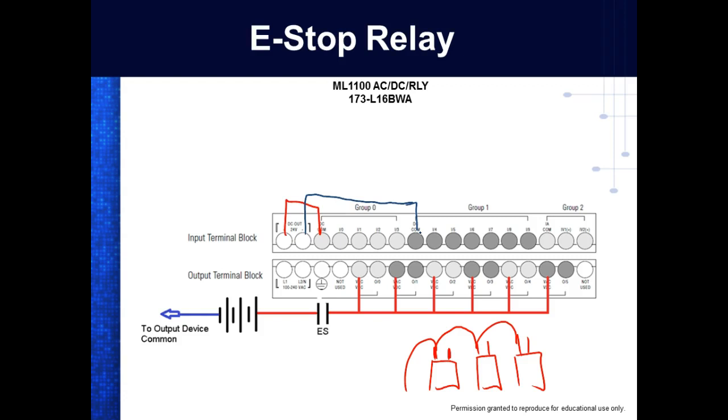Now this PLC, the one we got, runs relay outputs. What relay outputs means, it don't care what you put out there. You can put DC, you can put AC, so you can set them up for source, you can set them up for sync, or you can set them up for AC. All you'd be concerned with is the maximum voltage that these relay contacts can handle, right? So right now I've got mine set up for sourcing output.